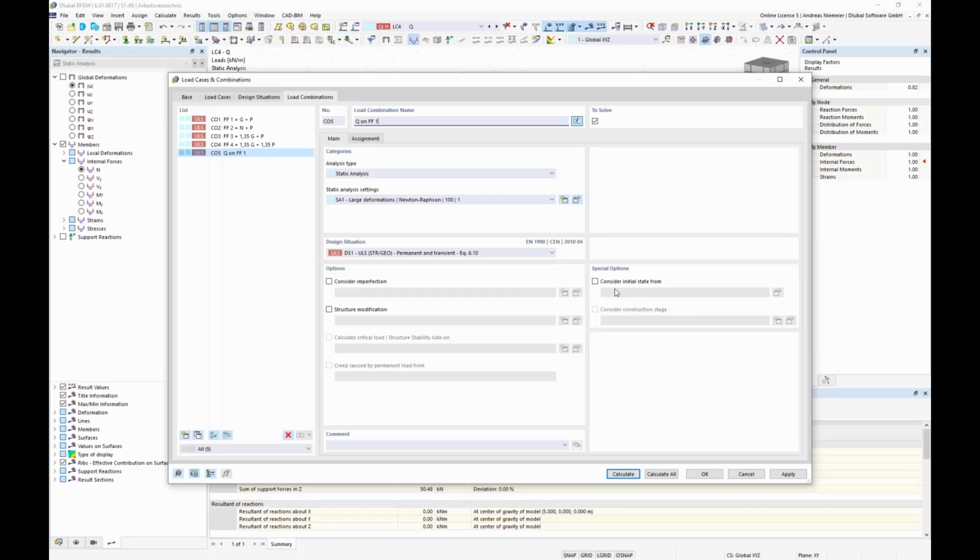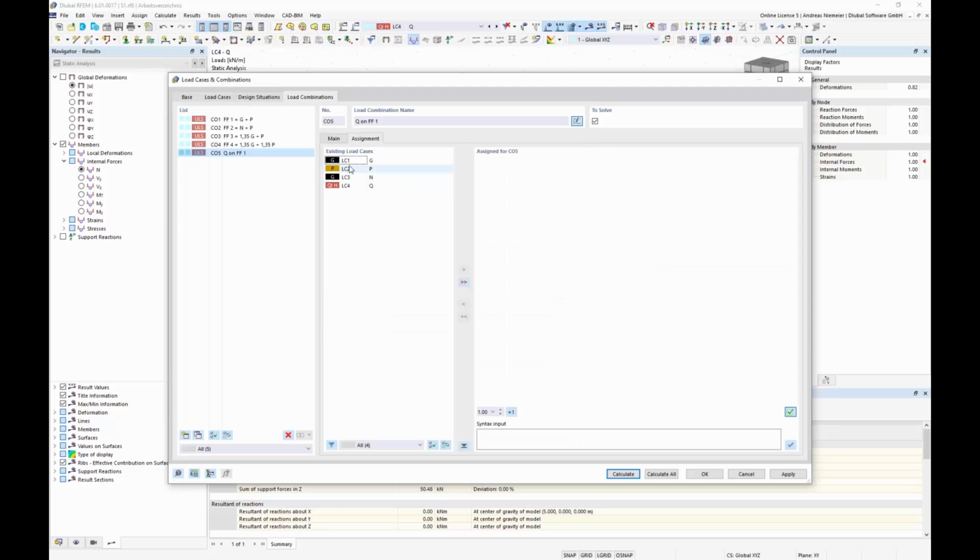So here you specify the shape, for example shape 1. This means we overtake the geometry of mesh and the inner forces, and to get a full set of calculation we apply also the outer loads, form finding loads and the expected, let's say, additional load.